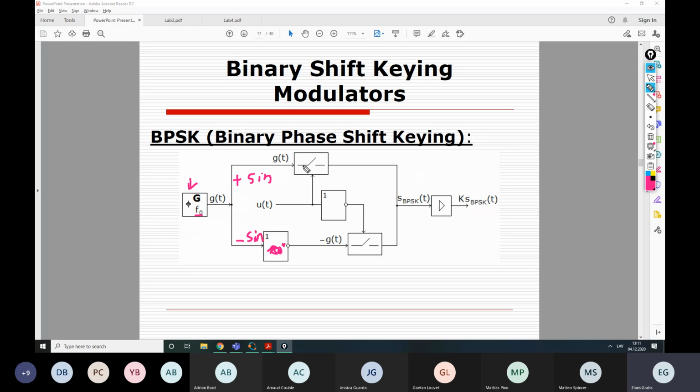So either one of them is open and the other one is closed always, right? It only changes which one is open, but there is only one open switch at the same time. We are not considering any delay in this element also, right? So this is a logical inverter, which converts 1 to 0 and 0 to 1, vice versa, right?